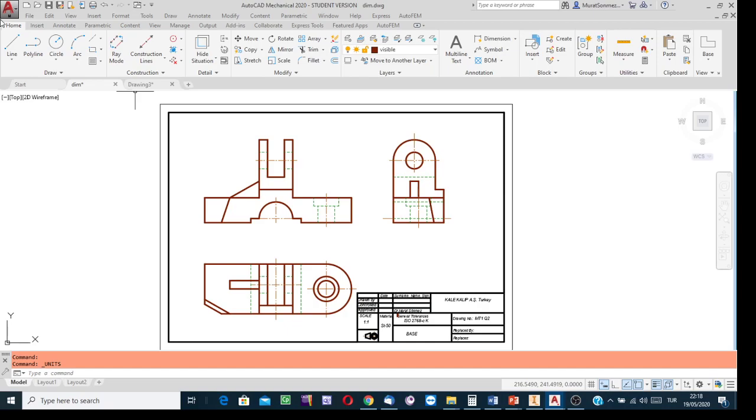Unfortunately, in this old-fashioned software, it is a fact. So since it is so, and having the paper 10 times bigger than the standard size is really a poor practice and quite misleading, well, changing the unit system, selecting the unit option and bringing up the unit changing dialog box is certainly not my method. My method is different. Do not change the units. At the dimensioning stage, change the unit of dimensions.